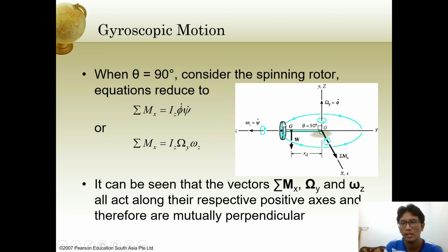But what happens if we add weight right here? What happens if we change the disc with another disc which has higher weight? The spin is constant. We cannot change the spin, but the precession will automatically increase. The precession speed, this omega, will increase. We will rotate faster.